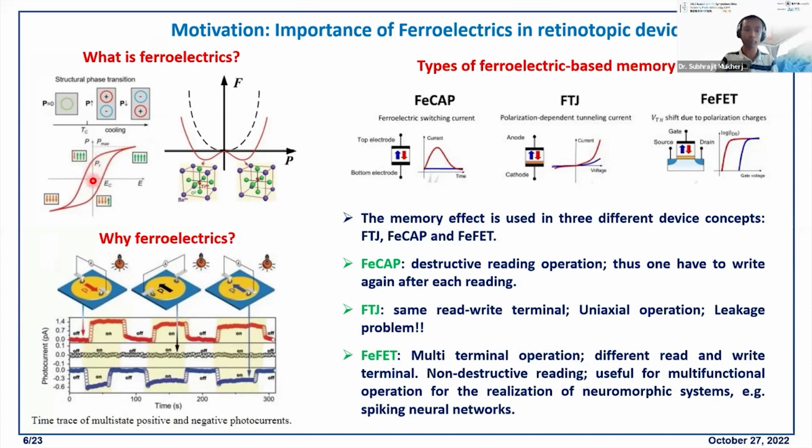This is called the remanent polarization. You need a negative, or opposite polarity, electric field to destroy these dipoles. This is your coercive field. Above the positive coercive field you have a positive polarization, and beyond the negative coercive field you have a negative polarization.